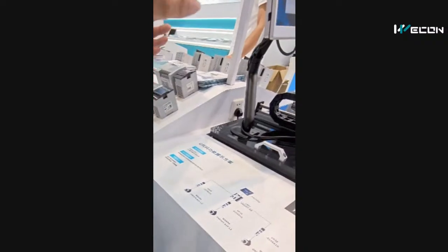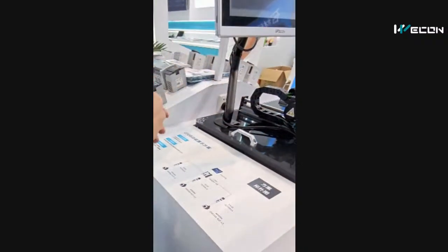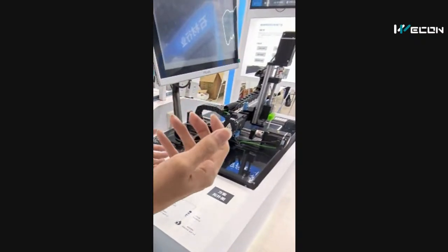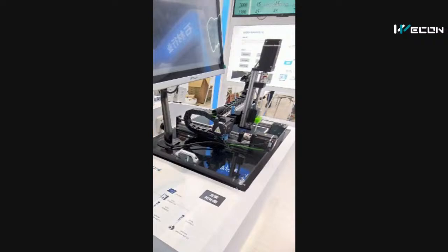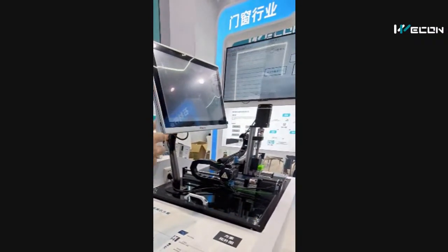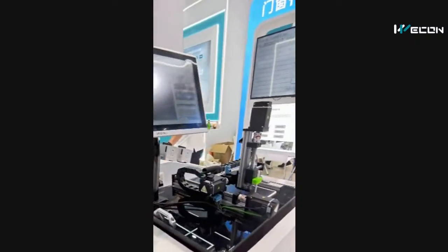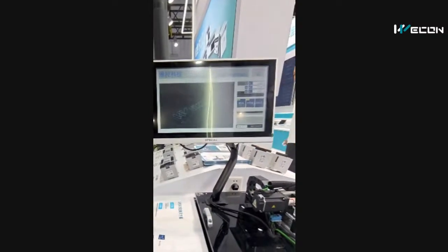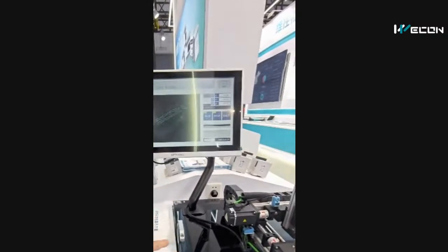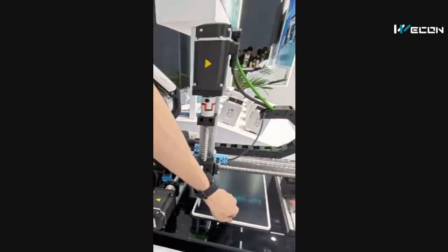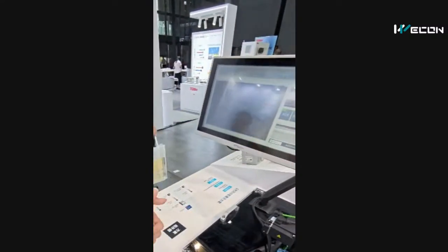G-code function. So this solution supports the customers to import the G-code file, import the CAD file. Then the Lua screen in the HMI will evaluate and read the CAD file and export the X, Y, Z position of the movement, so that this could achieve the movement.